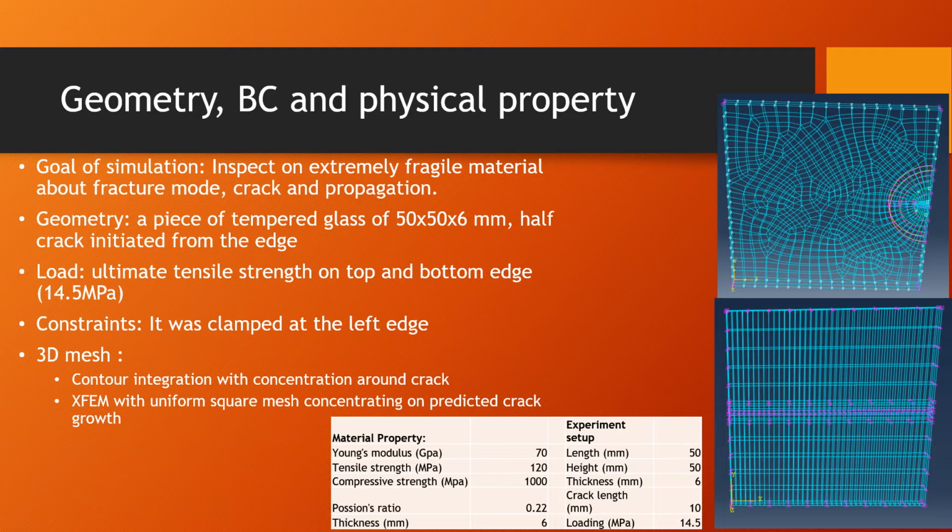For the 3D mesh, I use contour integration for the stiffness calculation, and I need reinforcement around the crack to solve the convergence issue. And XFEM is used for crack development inspection.